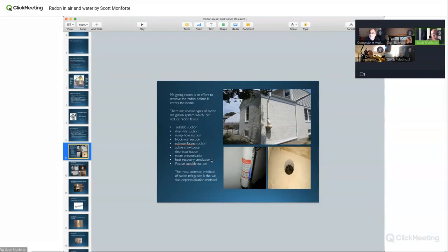It'll work better. So when you have builders putting these systems in, and all of a sudden they say, oh, the radon's high, come in, and can you do what you have to do? I go there and ask, where's the attic? And they ask, what do you mean? I say, I have to get up in the attic to put the fan in the attic. And they say, there is no attic. So what they've done is run the pipe up through maybe a vaulted ceiling, cathedral ceiling, up into a finished area of the attic you can't get to. So they say, oh, you just put it in the basement.